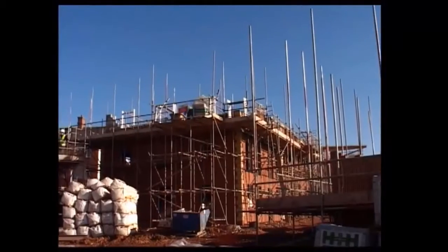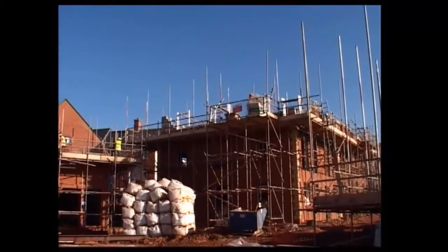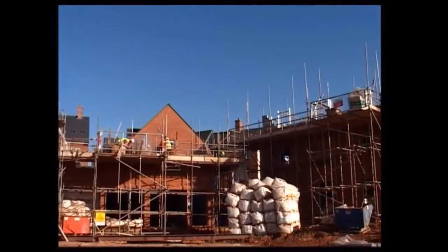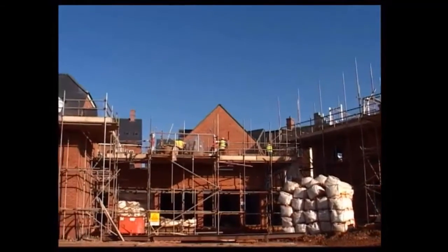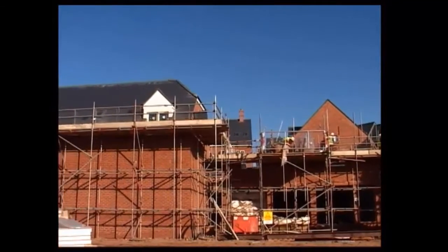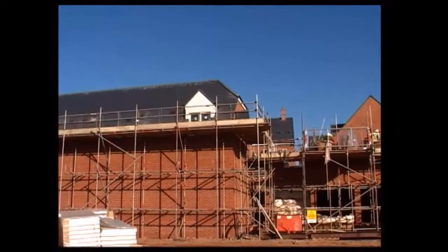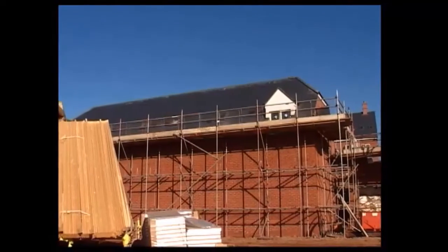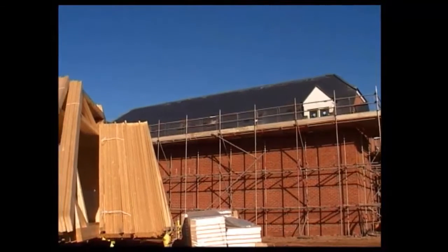Because the screed is separated from the slab, it needs to be slightly thicker to prevent the risk of cracking. Since the 1990s, most ground-bearing slabs have had floor insulation of some sort. Before this, uninsulated ground floors could account for 10 to 15% of total heat loss. There are a number of insulation options. Choice depends on the type of heating system, the nature of the insulation, and the preferences of the designer.